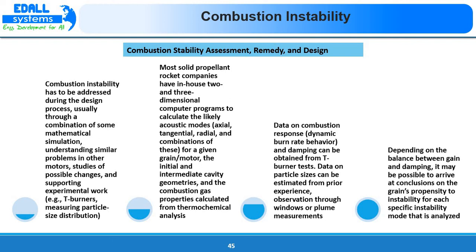Most solid propellant rocket companies have in-house 2 and 3-dimensional computer programs to calculate the likely acoustic modes, maybe axial, tangential, radial, and combinations of these for a given grain motor. The initial and intermediate cavity geometries and the combustion gas properties are calculated from thermochemical analysis. Development is happening to address and understand these instabilities using numerical and analytical approaches. So some of the major companies have in-house 2 and 3-dimensional computer programs to calculate these likely acoustic modes.